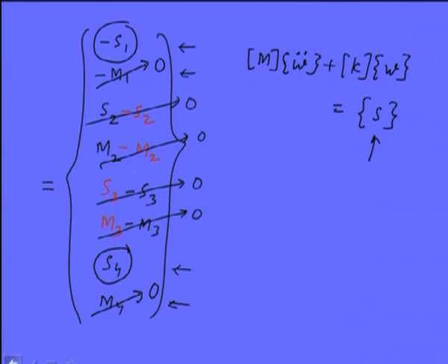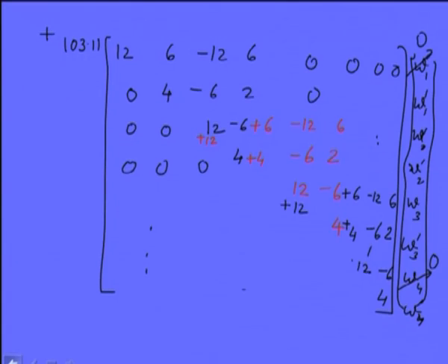And if you go back to the previous slide, you can see that W1 is 0. So when we multiply this vector with the matrix K, this whole column will be multiplied by 0. So it will not contribute anything. Similarly, W4 is 0, so the last but one column will not contribute anything because they are getting multiplied by 0. So we need to eliminate them.